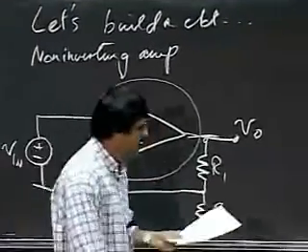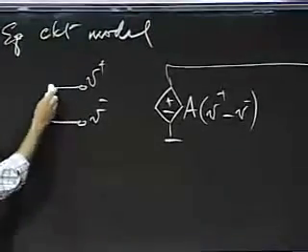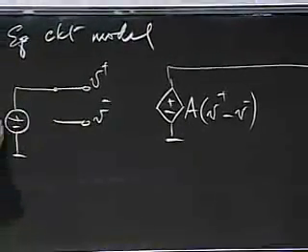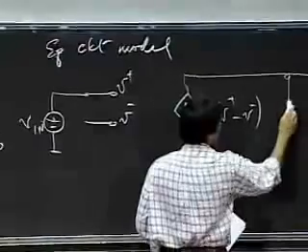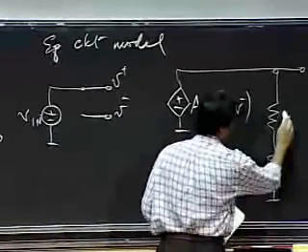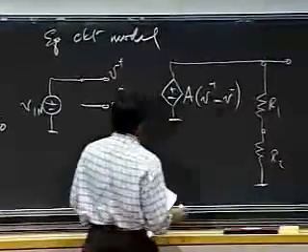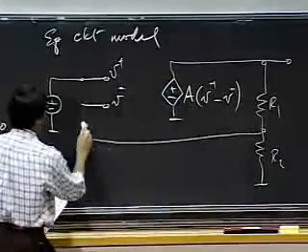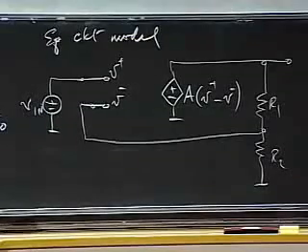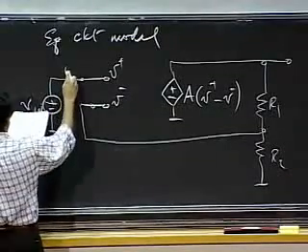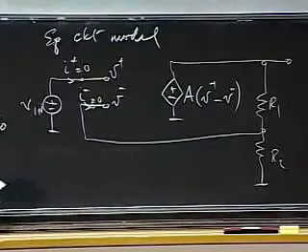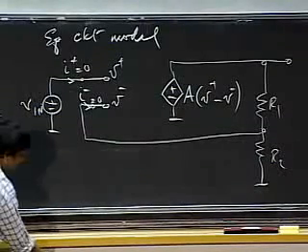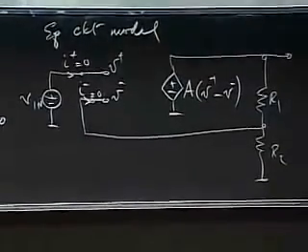So I draw that for you. And then I connect my V in here. And remember, I have an R1, R2 resistive divider here, and this one gets connected to this terminal there. I also know that I plus is 0, and I also know that I minus is 0. All I've done is simply replace the amplifier with its equivalent circuit.